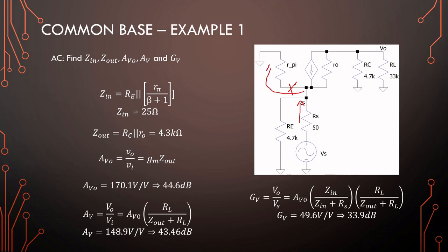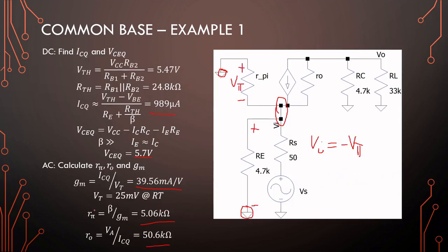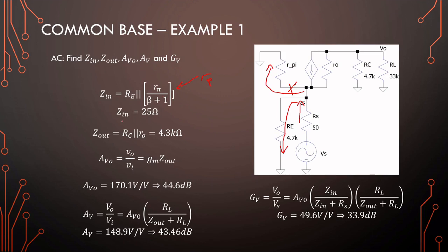Okay, so we are seeing this resistor, and we are seeing this resistor, and since both of them are going to ground, they are in parallel. But we are seeing R pi beyond this cross that we draw. So this is just R pi divided by beta plus 1, or, per definition, small re. Sorry, it's difficult to write with the mouse. So it's re parallel with re, or if you calculate it, R pi just divided by beta plus 1.